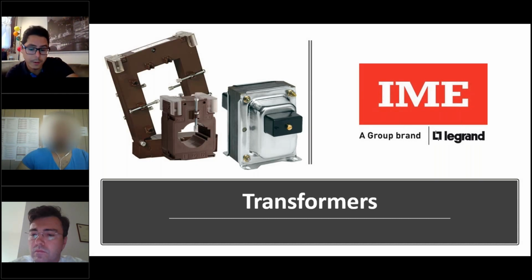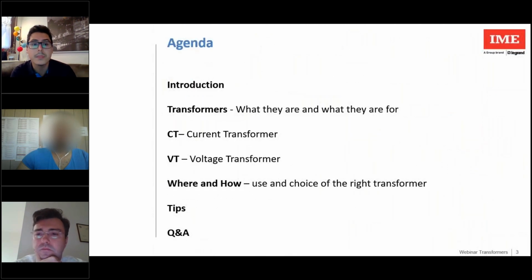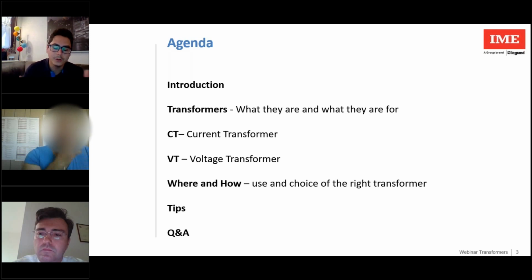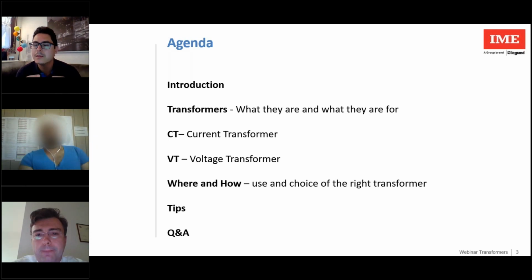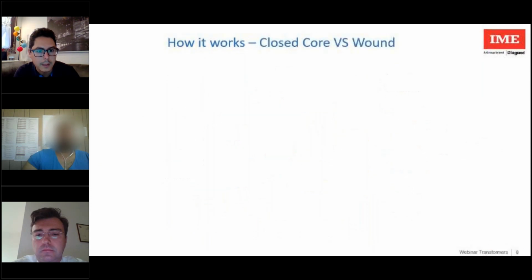With the primary winding, you find the accuracy transformer for 100 amps. If you want a current transformer with passing cable, you can't use this one, because the magnetic field generated by 100 amps is not enough to have this type of accuracy. You have to use the primary winding that you see in this slide.